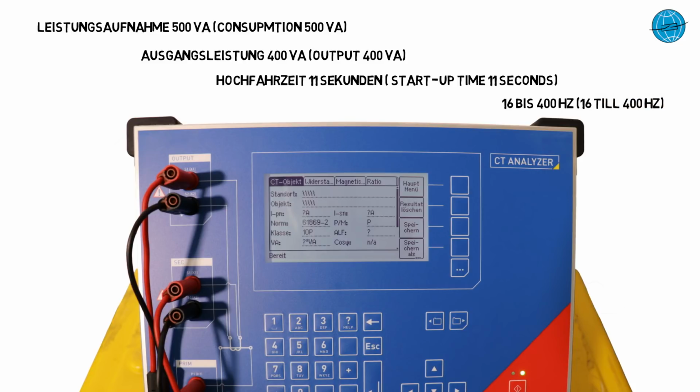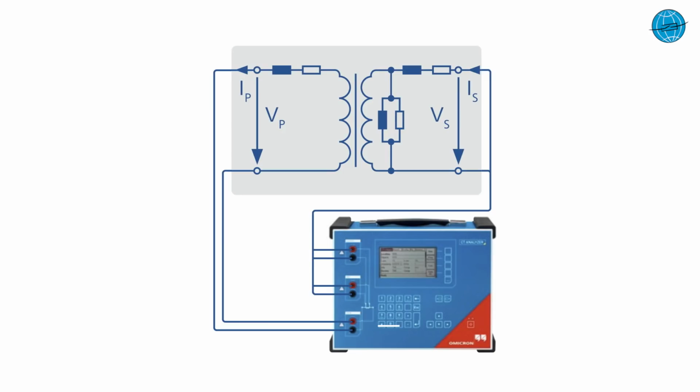This covers every possible application from railways to aviation. Due to secondary testing, it doesn't require heavy cables on the CT Analyzer, which would otherwise be required for high ratios or high knee point voltages. The low voltage measurement method works here because of a smart lowering algorithm of the frequency during the measuring process.